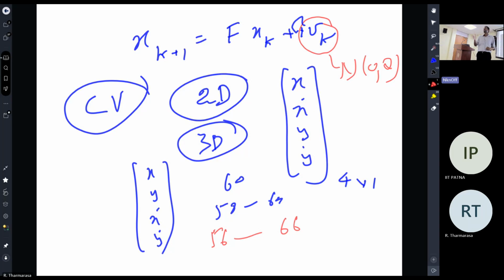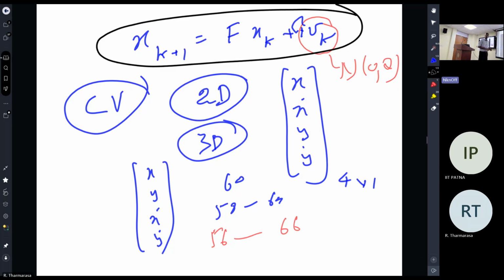So what is the challenge with the pedestrian compared to tracking a vehicle? What is challenging in this equation? When you track a pedestrian, what is challenging over here? Unpredictable. How do you translate that statement into a mathematical equation? Process noise, right? If you use a constant velocity model, this has to be really high, because a pedestrian can go and turn sharply.